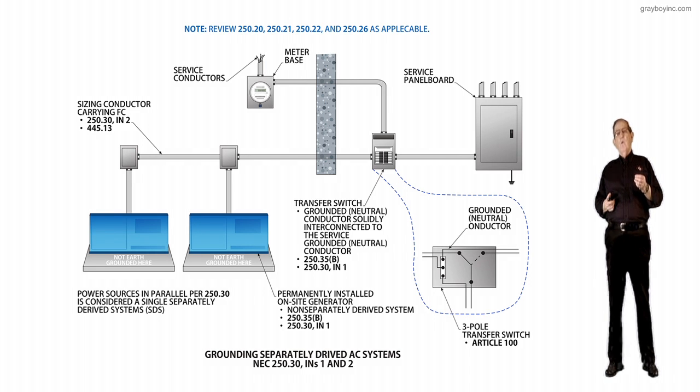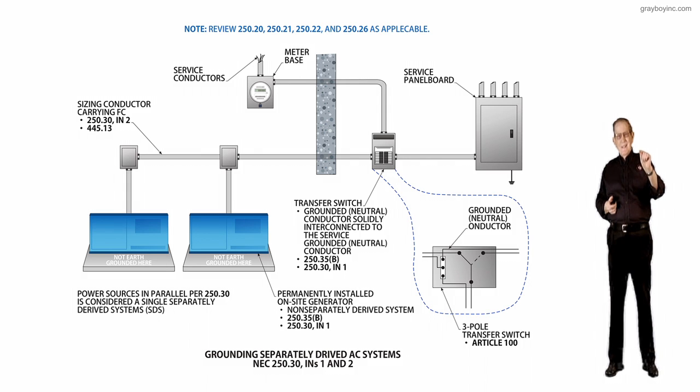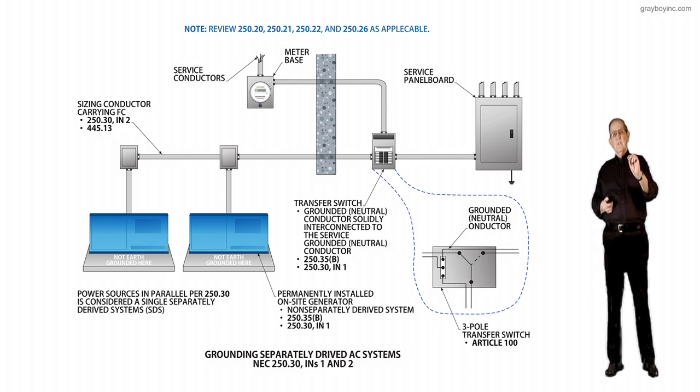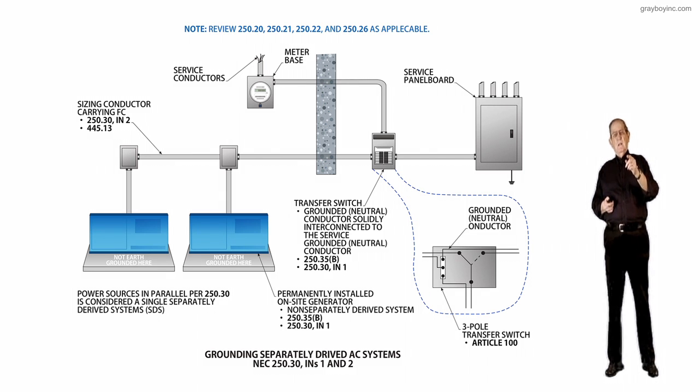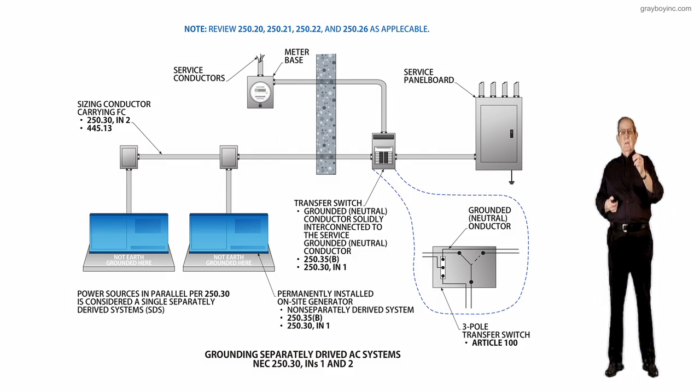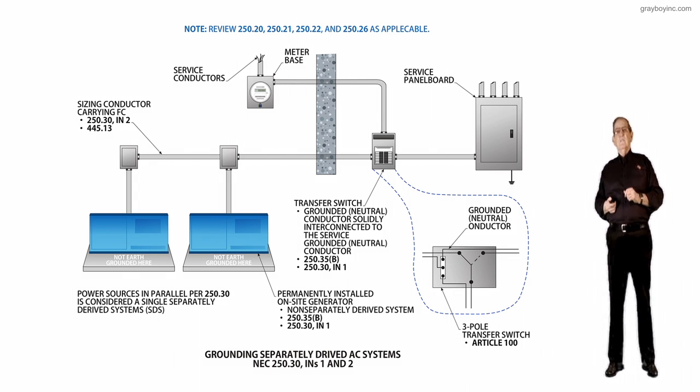You go to 701.2 and look at the informational note, and if you can delete some of those emergency type loads, egress and so forth, and only supply those loads listed in the 701.2 informational note, then you're a legally required standby generator. If you can delete some of those loads in 701.2, you can become an optional standby generator in accordance with the 702.2 informational note. So that's basically how the designers will classify it.